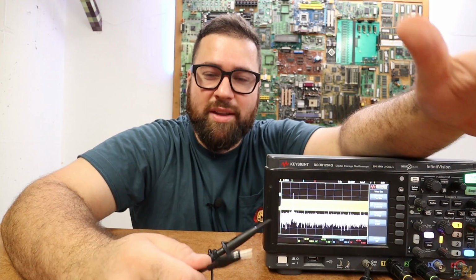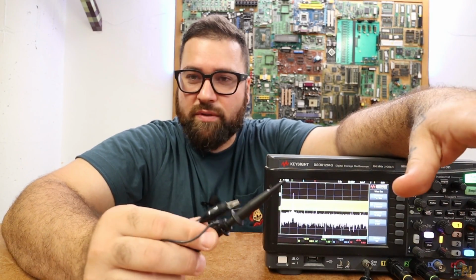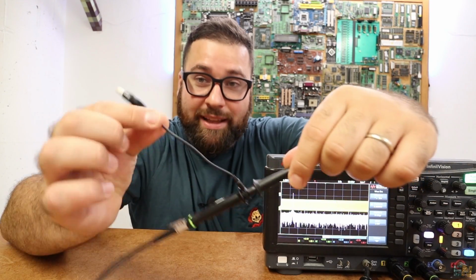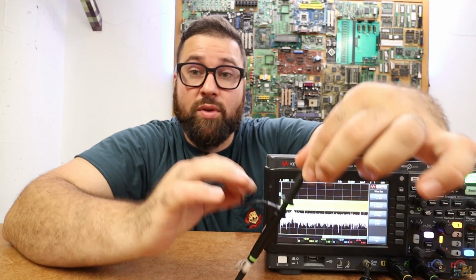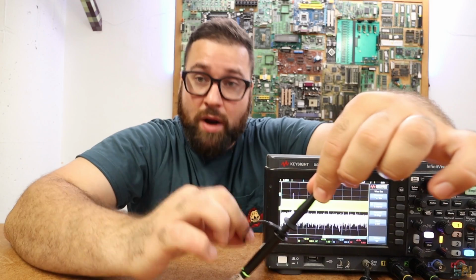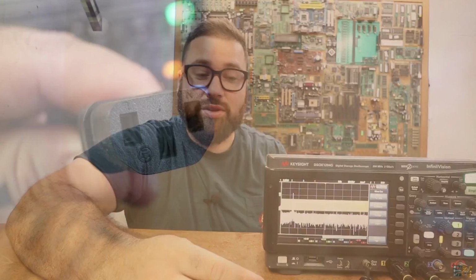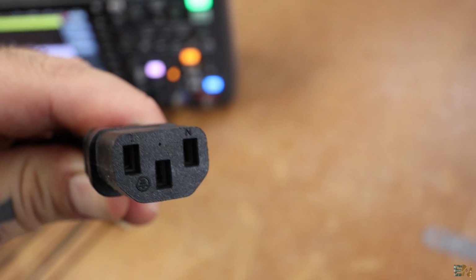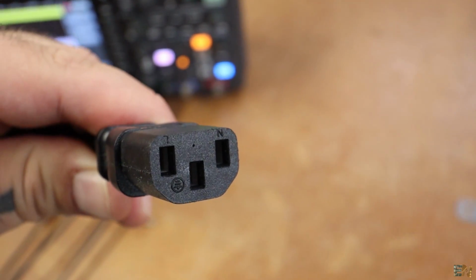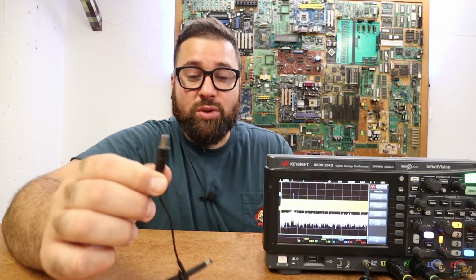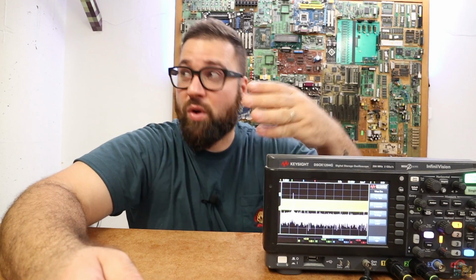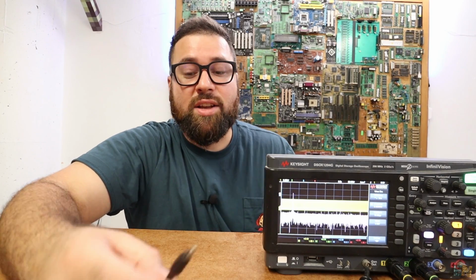And now, things to have in mind when using your oscilloscope. First of all, for safety reasons, you have to know that this is actually the ground of your oscilloscope. It is connected to the ground, the same ground that is shared with your main power input. So if you connect this to your main outlet, it's sharing the ground. If by mistake you connect this probe, which is the ground, to the phase of the power outlet that you are measuring, you connect a short circuit between your phase and the ground of your home, and your breaker will jump. And if you don't have a breaker, it will make a short circuit. So be careful with that.